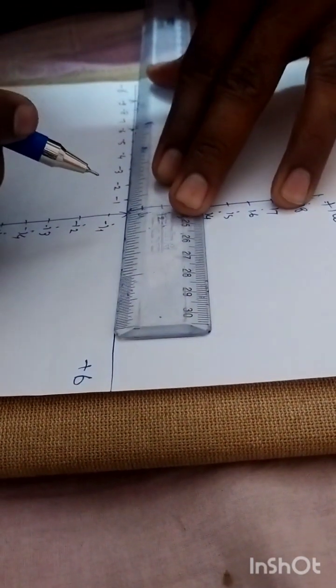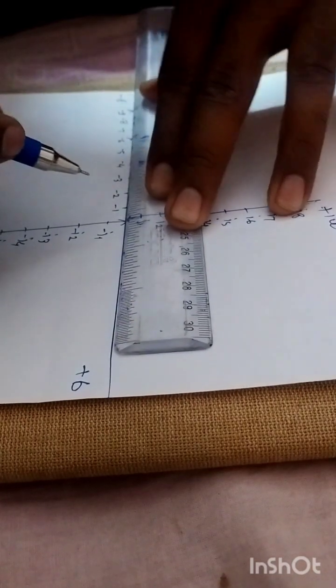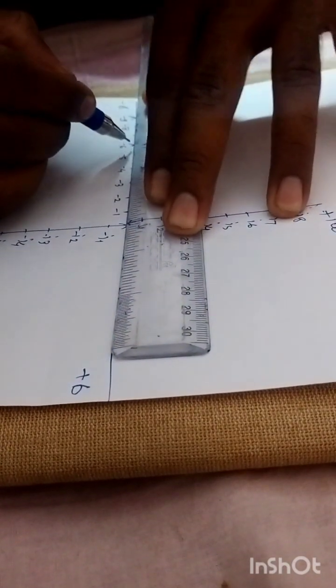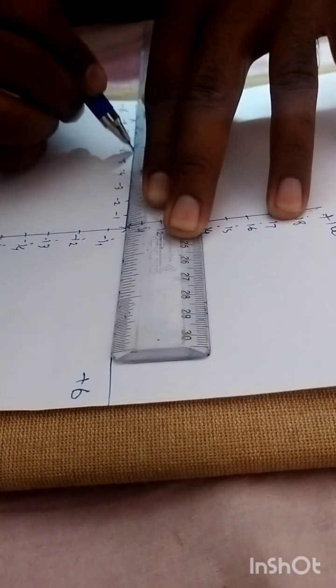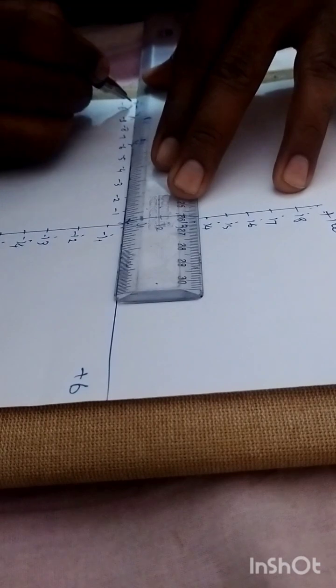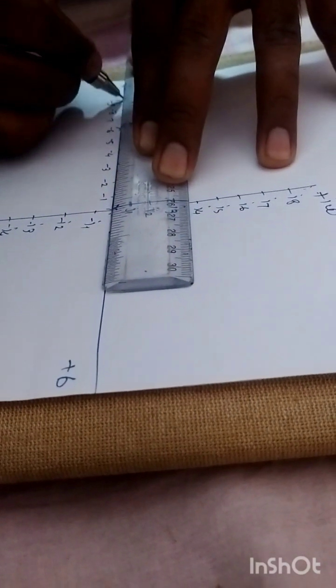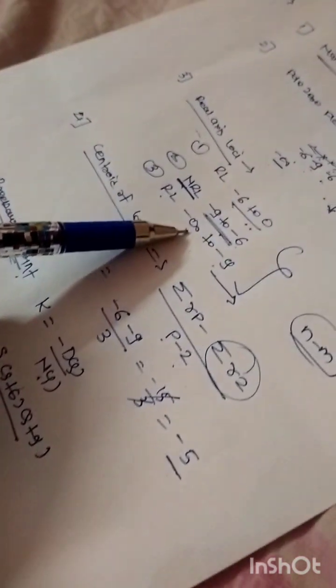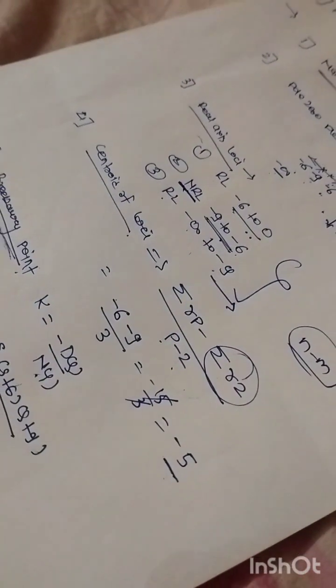After that, as we know, this portion is highlighted, which lies between minus 6 and 0, because there will be a significant presence of the root locus in this interval, right? Similarly from minus infinity to minus 9. According to our step number 3, real axis loci, it is accordingly taken into account.